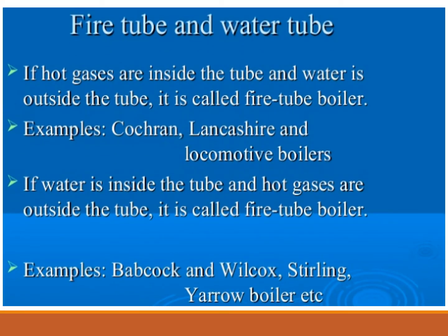Fire tube boiler and water tube boiler. In fire tube boiler, hot gases pass through tubes which are surrounded with water. In water tube boiler, the water circulates through a large number of small diameter tubes and hot gases flow around them.